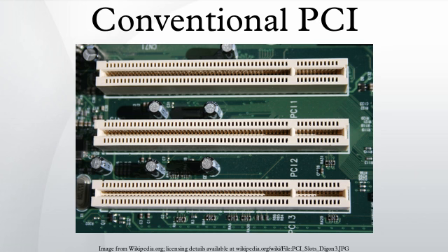The starting address must be 64-bit aligned. That is, AD2 must be 0. The data corresponding to the intervening addresses is carried on the upper half of the AD bus. To initiate a 64-bit transaction, the initiator drives the starting address on the AD bus and asserts REQ64 at the same time as FRAME.